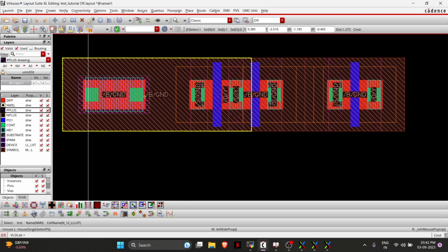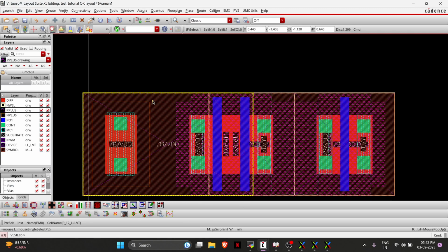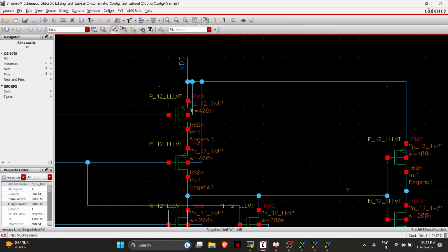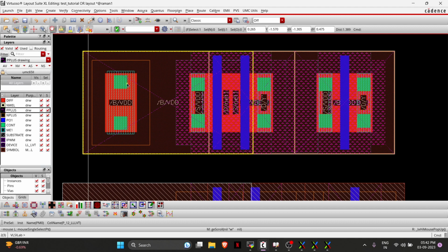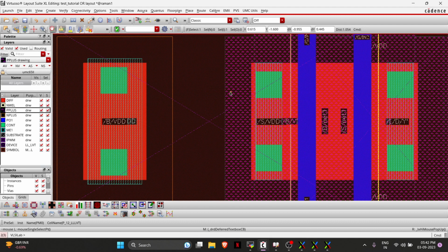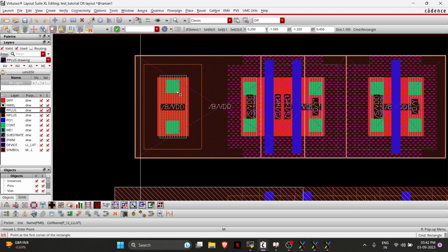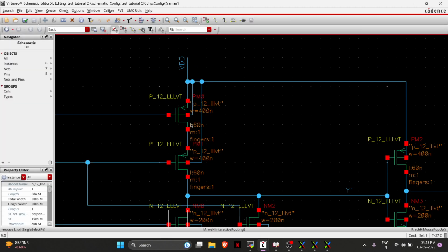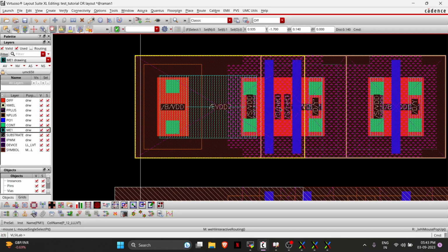Oh yeah. Here it is showing ground. It's showing VDD. Now let's start from here. This VDD will go to the source of this PMOS. So let's take more angle, or what I can do is straight up click and connect this. It is connected to VDD. Source of this transistor is connected to VDD. Okay, drain is already connected.